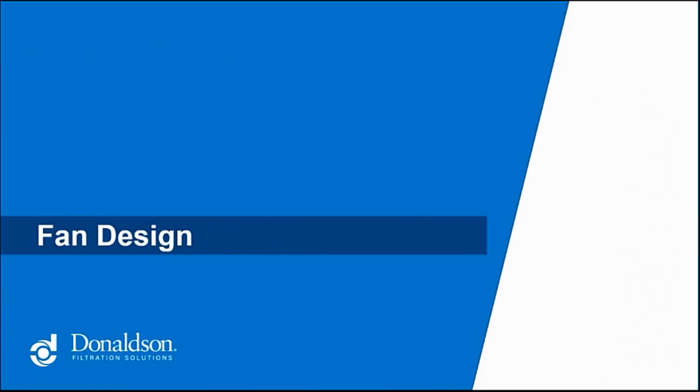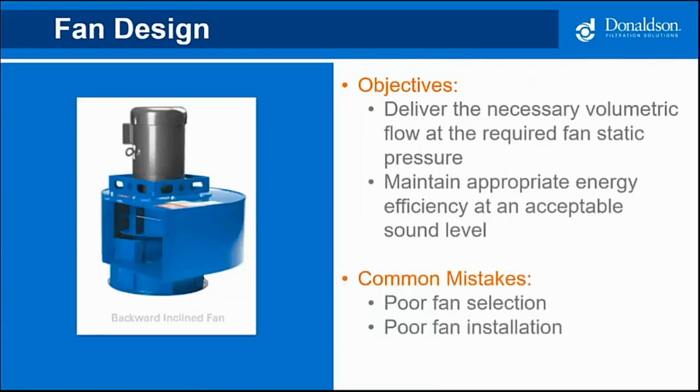Thank you, Ashley, again. Okay, fan design. Again, this is the fourth component of industrial ventilation design: hood, duct, collector, and now blower. Objectives: volumetric flow at the required fan static pressure. Many people miss that mark. We also want to maintain energy efficiency, so we don't want too much, but we can't have too little. And we want to make sure of the noise level.